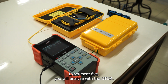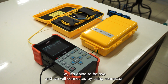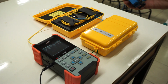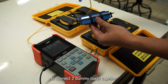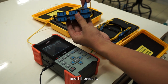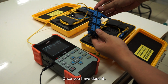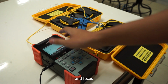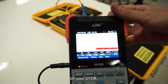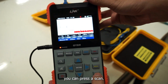Experiment 5. Event analysis with OTDR. We will use more dummy loads, so it's going to be 2. We will connect them using a connector like this one to join the 2 dummy loads together. Once you have done that, focus on your OTDR and, once again, press scan.